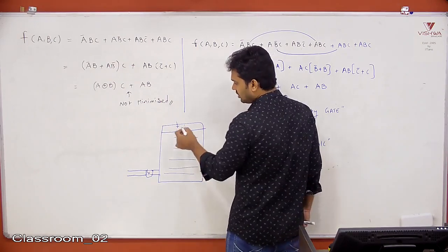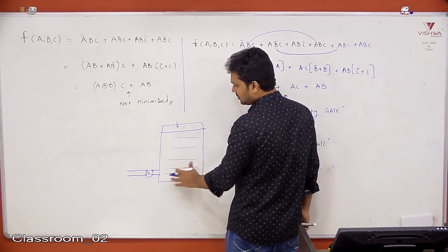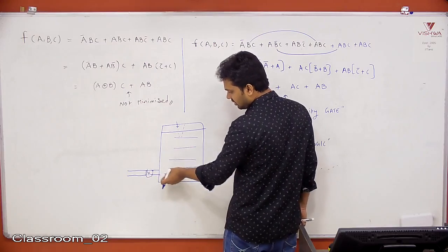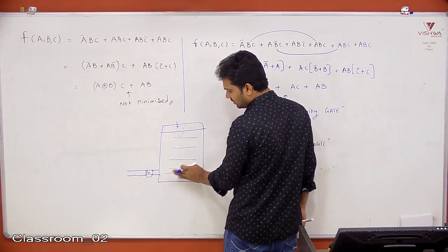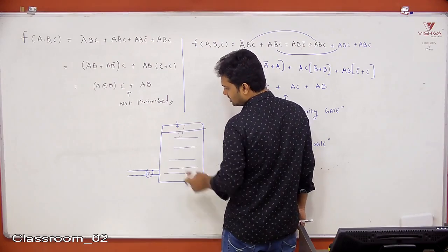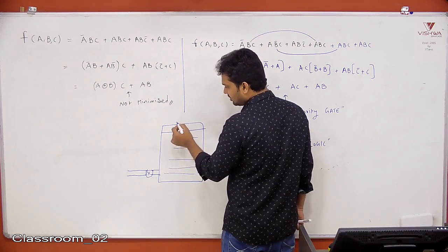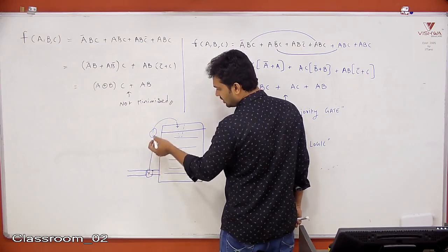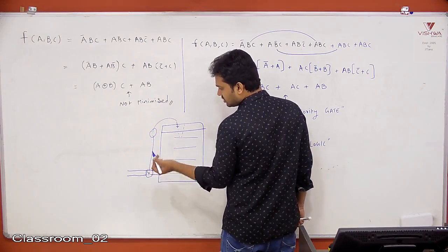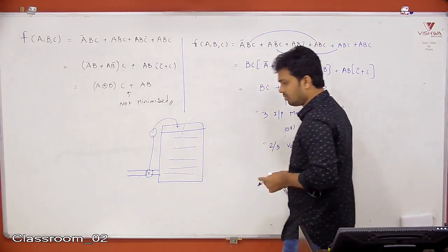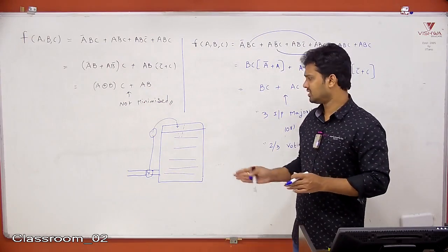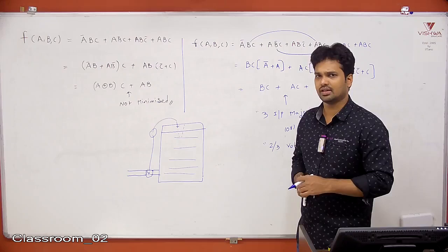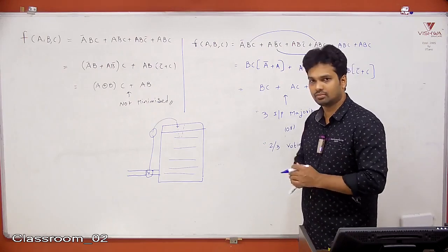So here, this is say a simple control logic. Just liquid is flowing through it, that may be acid or something. Whenever it reaches some level, I should close it. I have designed some level switch. That switch will take the feedback and it will be used to open or close the valve. But if it is a critical industry, very high concentrated acid, it should not overflow.